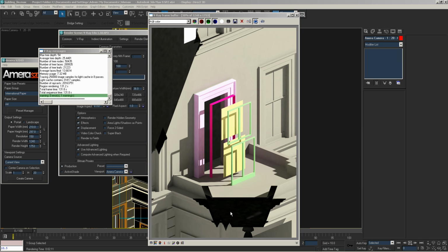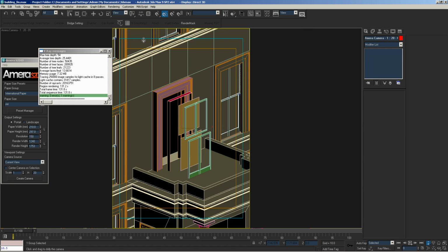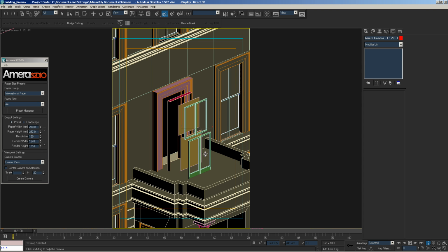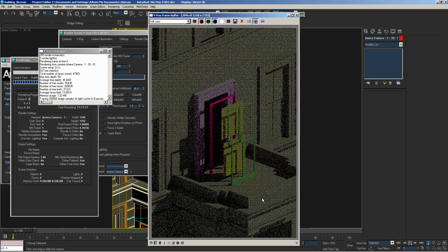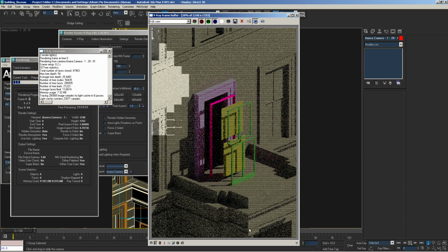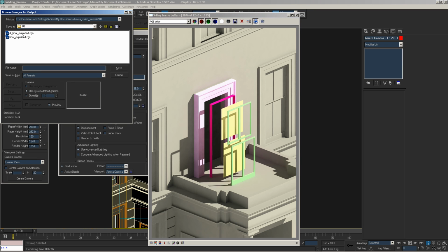As we can see, there is an unwanted clipping that occurs. This could be fixed by selecting on the bottom right corner the option to move the dolly camera and the target. When we move the camera using that option, we don't actually zoom out, but we just move the camera and the target together. Since this is an orthographic camera, it will keep the same scale of the object. Just move the camera cone backwards so the clipping wouldn't occur. Now let's render the view and see the effect of that workaround. Good. Let's save this render for further editing.